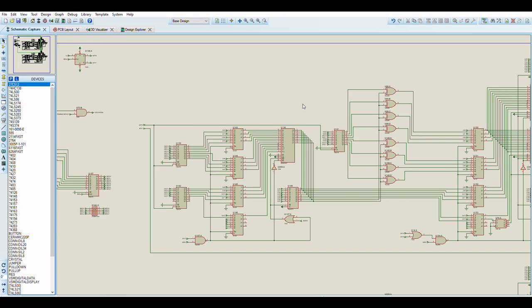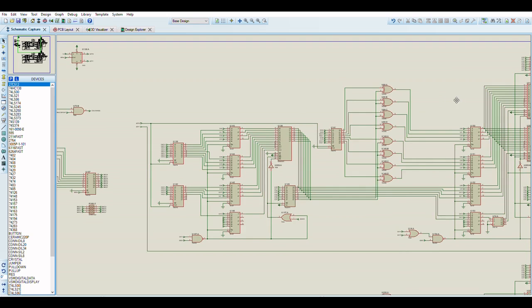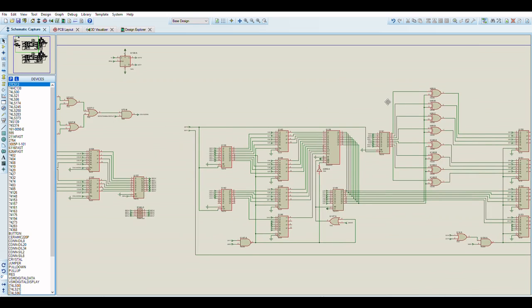So it all works out in the end that I just have one large virtual tile screen for the tile index, and then all of the other maths works out where I can use the lower 4 bits for the X and Y tile position to then index into the tile RAM based on the tile index plus flips for the horizontal or vertical flips. So this is what this circuitry does.